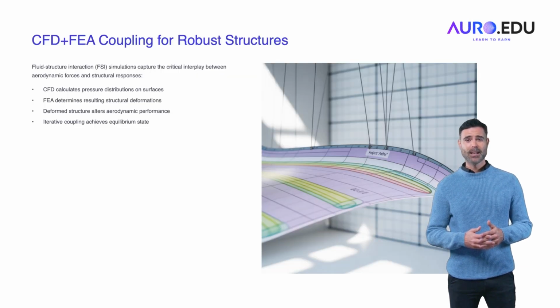CFD and FEA coupling for robust design. Coupling CFD, computational fluid dynamics, and FEA, finite element analysis, is essential for designing robust aerospace structures. Fluid structure interaction, FSI simulations, capture the critical interplay between aerodynamic forces and structural deformations. For example, wing deflection due to aerodynamic loads can significantly affect the aircraft's performance.